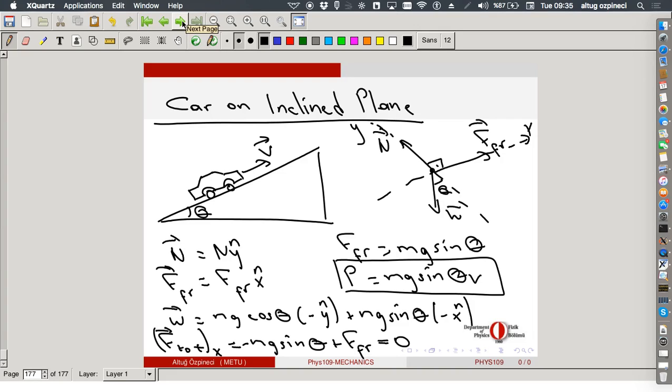It burns more fuel. You see, at every rotation, it burns a fixed amount of fuel, and that creates a given amount of work. If you burn more fuel per minute, you will be doing more work per minute. Well, work per minute is what we call the power. So if you lower the gear, you increase the rotations per minute. If you increase the rotations per minute, you will be burning more fuel per minute, and hence your car will have more power. And if it has more power, you can go uphill at a larger, more or less constant speed, even if you have a car that has a small engine.